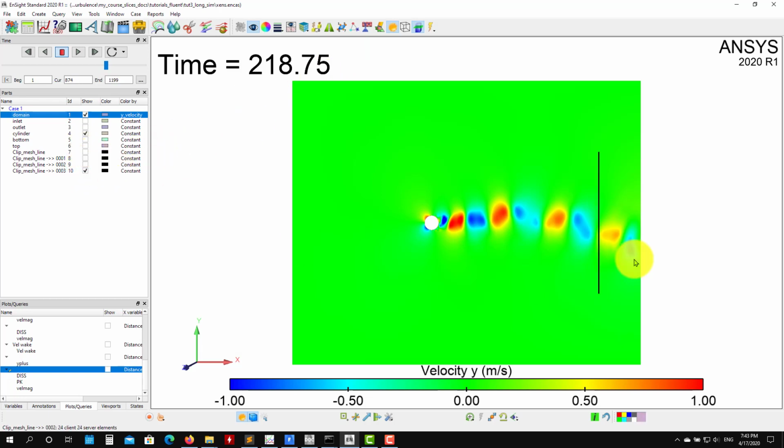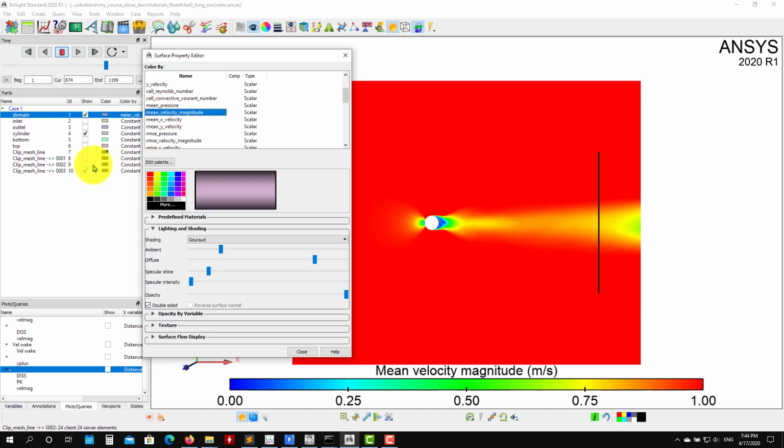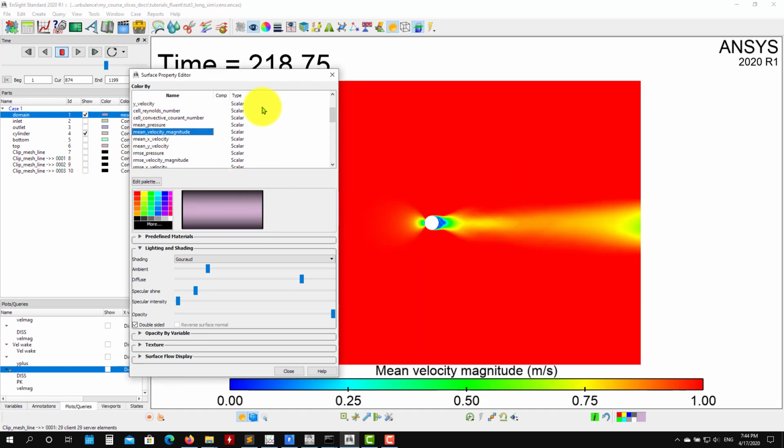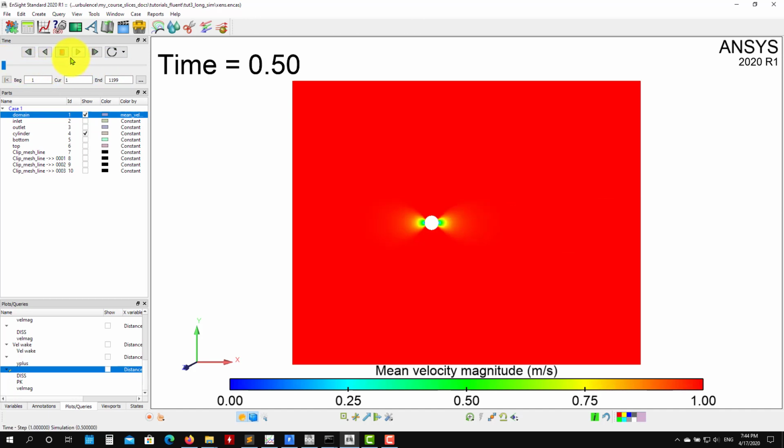For instance, now I will plot the velocity magnitude in this line here, just to see the wake. And okay, I also computed the mean statistics, so let me show you. This is interesting. So look at that, to know where you can start your sampling, it is also a good idea to save this information and visualize. So see that you start a simulation. So this is the mean quantity. This is computing all of your unsteady statistics, computing time averaging of everything.